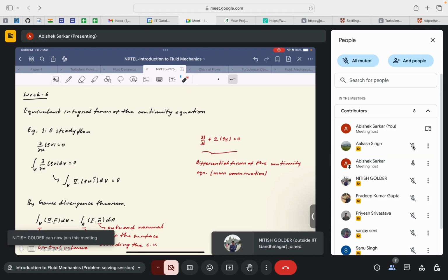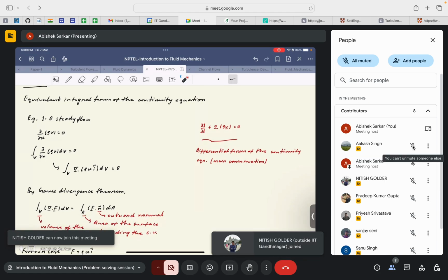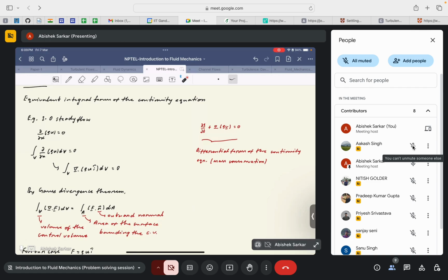So as I was mentioning, the governing equations that are inherently derived from the control volume approach would include a volume integral, and thus will be primarily in the volume integral form. Then, as one of the students was asking in the last class, we need to apply the Gauss divergence theorem to convert the surface integrals to a volume integral, and then find a net equivalent differential form of that governing equation, which we'll eventually see when we discuss the Reynolds transport theorem. That's why the concept of a differential form of the governing equation as well as the integral form comes into picture.